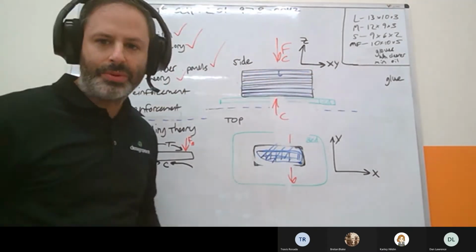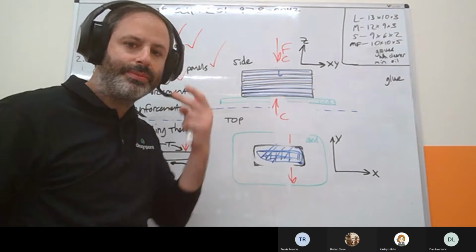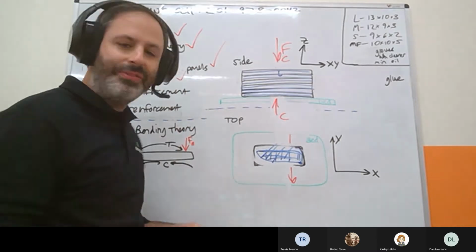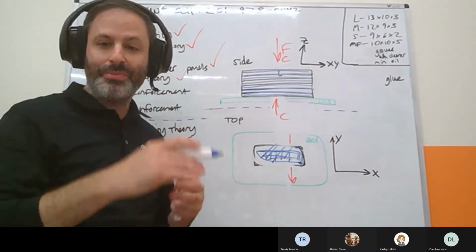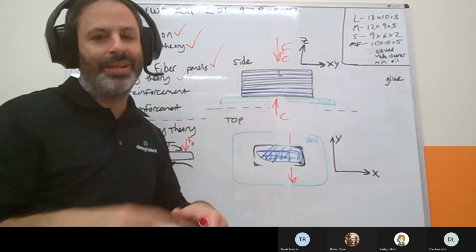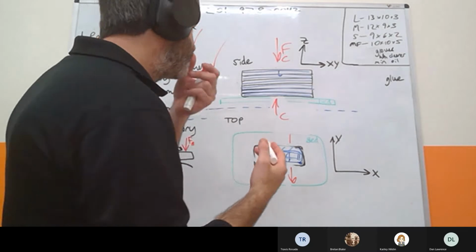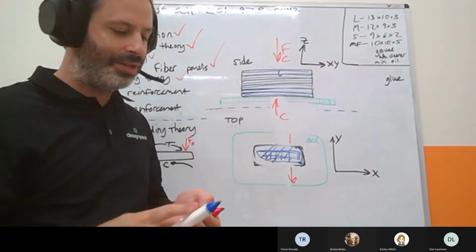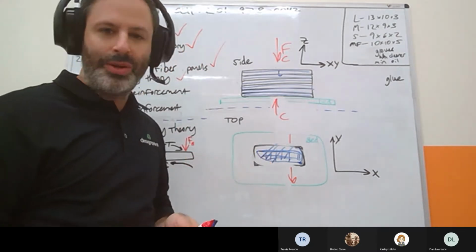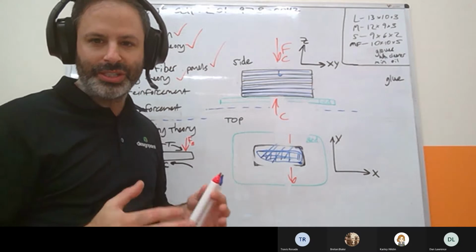So with stacked fiber, the trick is that you have to stack the layers all the way from the bottom all the way to the top. Or again, you're going to transfer the load to the weaker points. Now, this is an especially good strategy when reinforcing bolt holes. So this is very common.